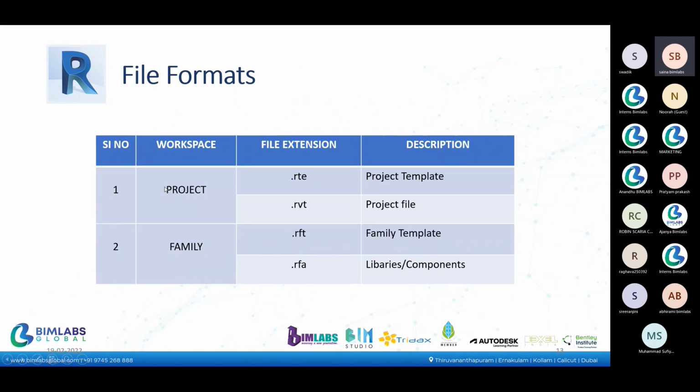In the project file format, we have two types of file formats, that is .rte and .rvt. Actually, the .rte file extension is used for the project template. I will tell you what a template is. Actually, the template is a workspace. I will tell you with an example.